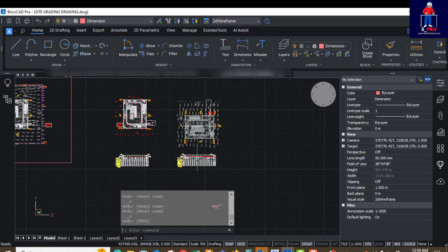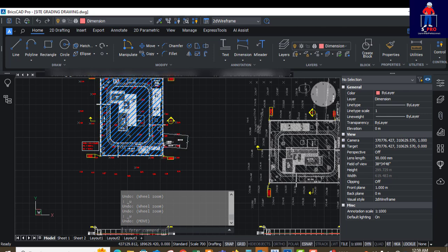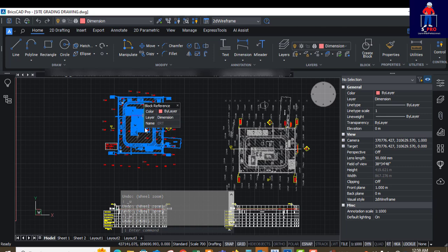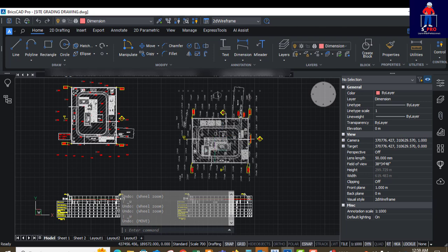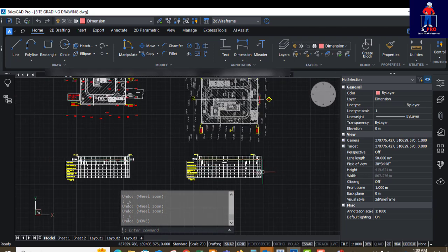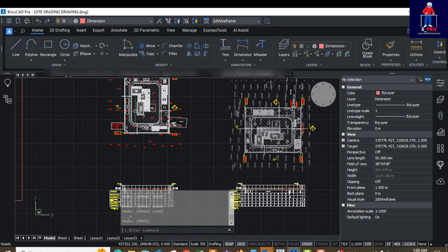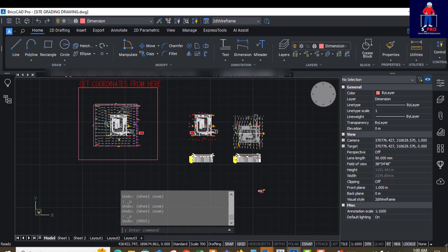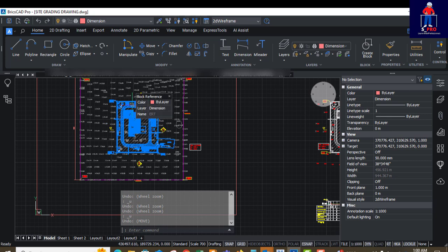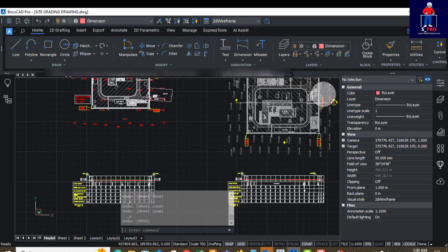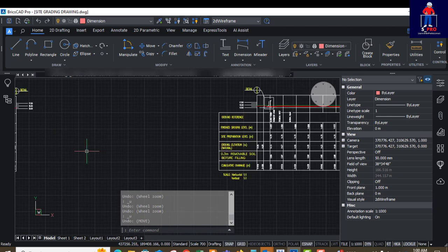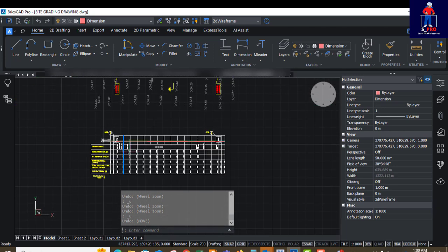But this time around, what I normally do is, if you look at this plot plan, this particular site location or site drawing is in the proper direction. But for me to actually get this, I need to rotate the site to align with the way I want my profile to appear. If you look at this, you see that I rotated it anti-clockwise, so that from my left to right, I will have my profile this way. The same thing we did for the other profile is what we are going to do here.